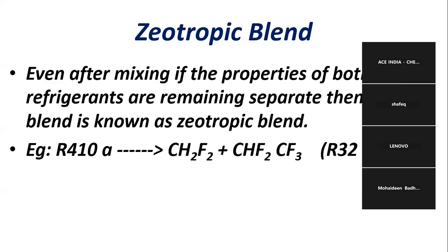So R407C is being used in many applications, and the performance can be improved with minor changes to the refrigeration system. That means adding some condensers. Generally, if you are adapting R407C into an existing R22 system, small minor changes must be implemented. Then once again, guys, the ODP factor for R407C is again 0 itself.